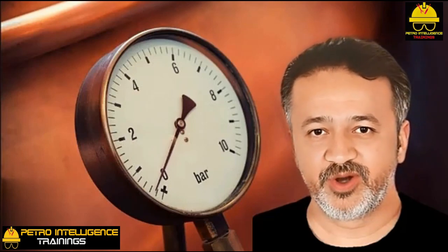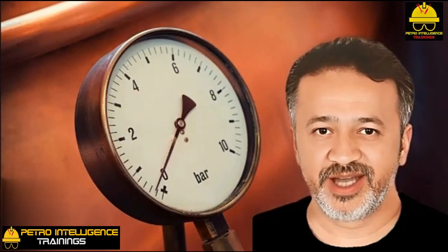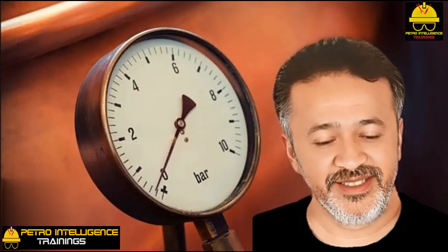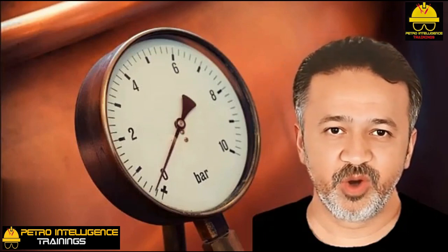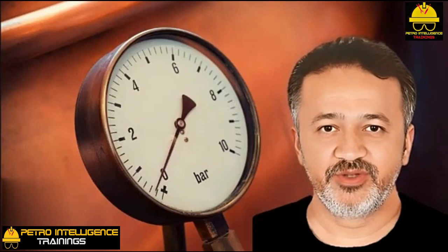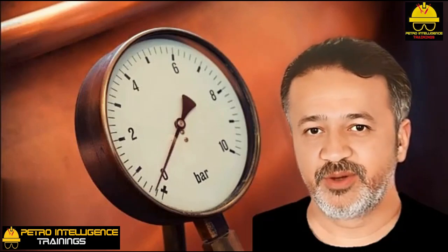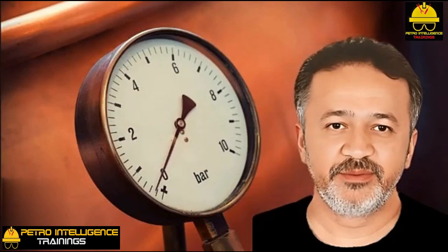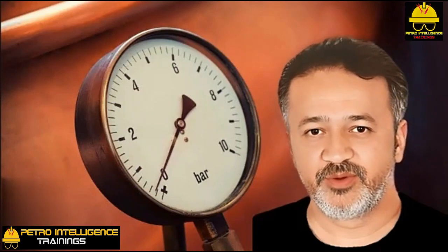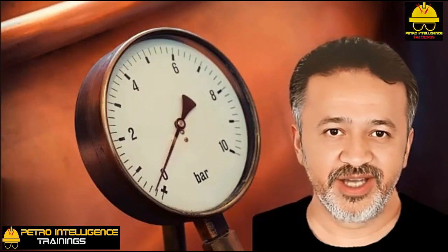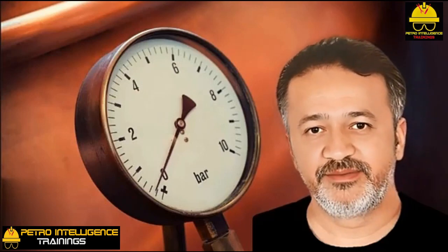To check the length of the thermowell, unscrew the thermocouple assembly and pull it out, then simply measure the length of the thermocouple. This is also a good opportunity to verify the control room reading with a portable temperature probe or a glass thermometer inserted in the thermowell. About 5% of the TI points used are not located where the unit piping and instrumentation diagrams, PNIDs, show them to be. Then, pulling the thermocouple from a point in the process sometimes causes an unexpected drop to ambient temperature at an entirely unexpected TI location.